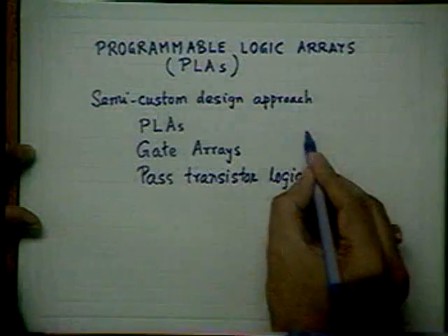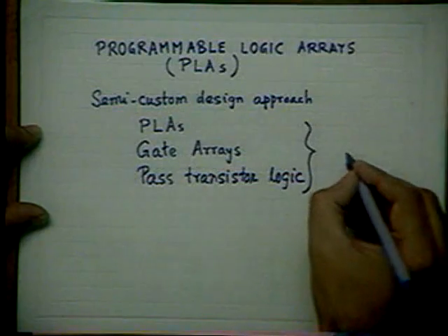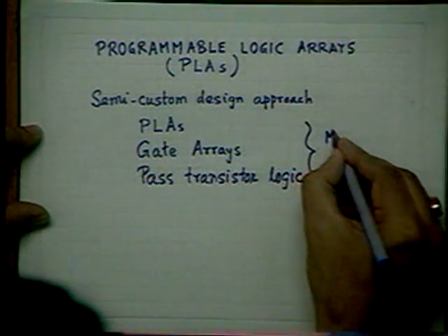It is already prefabricated. All you have to do is connect the transistors at certain node points wherever needed. So the entire design and fabrication cost is very low, and ultimately today I think you have come to know that these PLAs, whatever the programmability, are called mask programmable. These are all mask programmable.